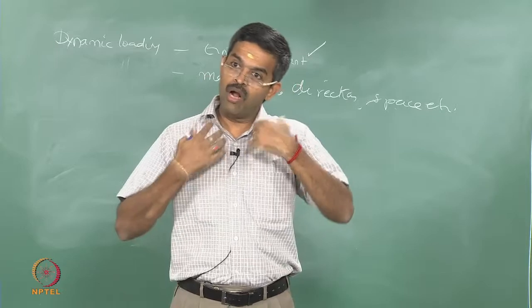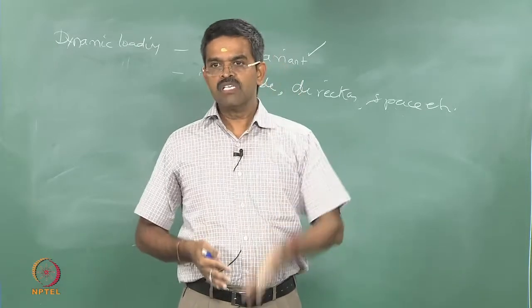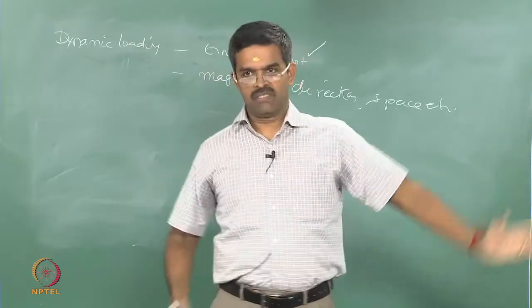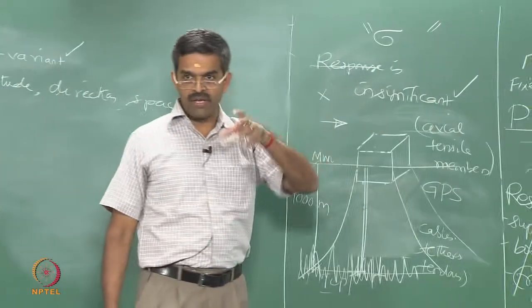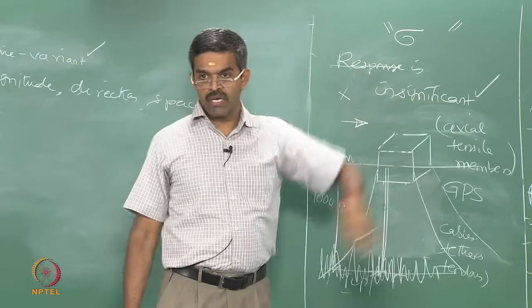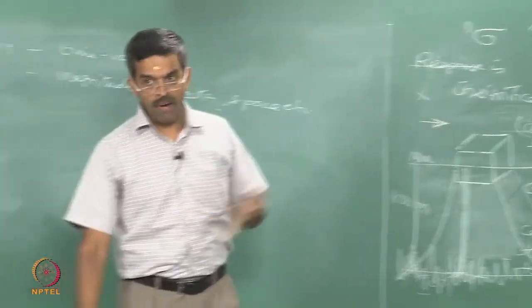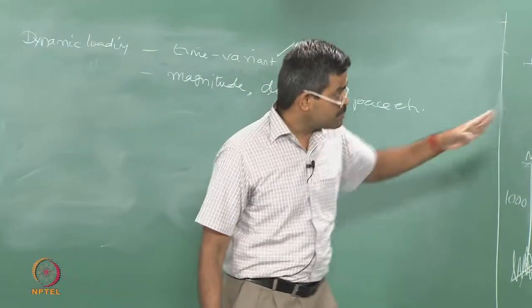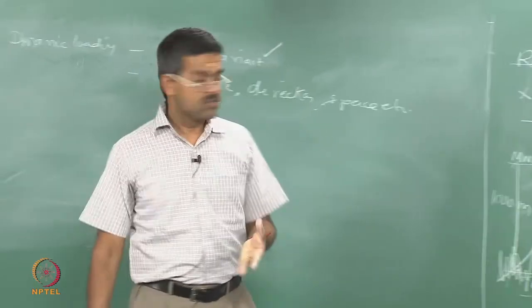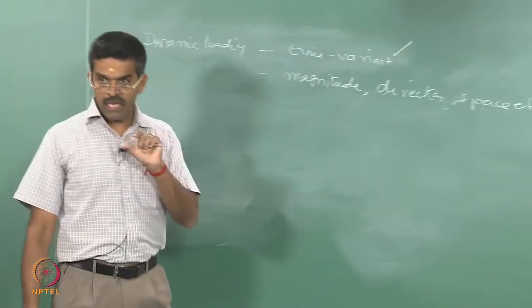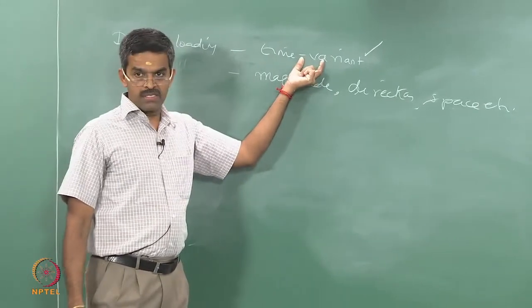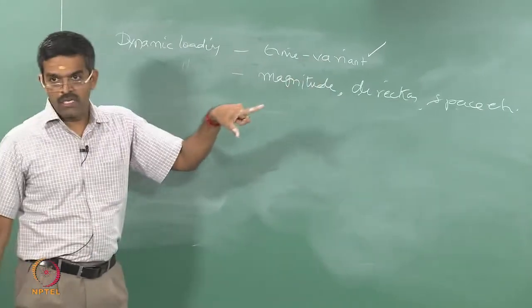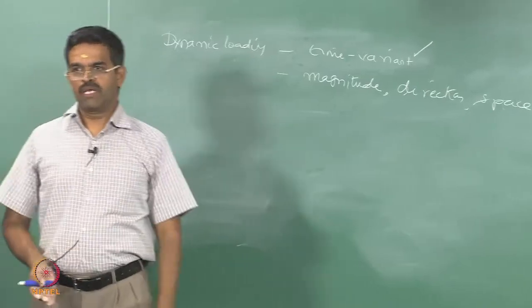Most of them did quasi static analysis, and the platforms were constructed. When the form started modifying from fixed to compliant and floating, people realized, yes, the mass is compromised, but the displacement response becomes very large. So, I have to do a dynamic analysis. It means the magnitude and the time variation, including the mass, are important for doing a dynamic analysis.